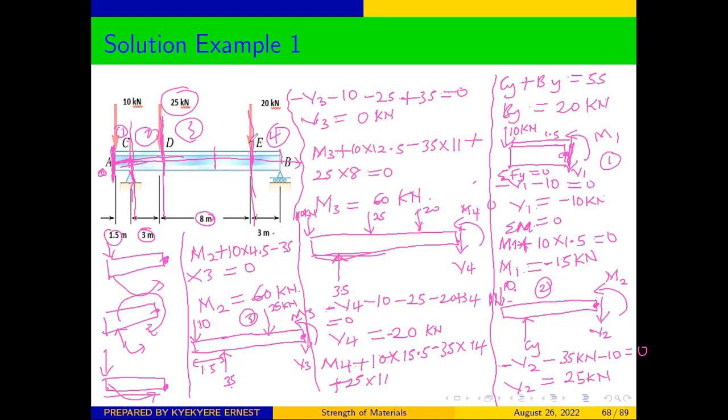Then we go to the last force, the 20, which will also produce anti-clockwise rotation, looking at its orientation. If we are taking the moment here and the force is applied up here like that, then it's going to rotate it in this direction, which is anti-clockwise. So plus 20 times 3, the distance where we are taking the moment, is equal to 0.